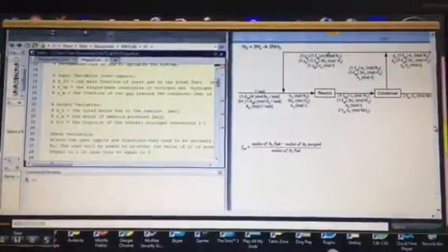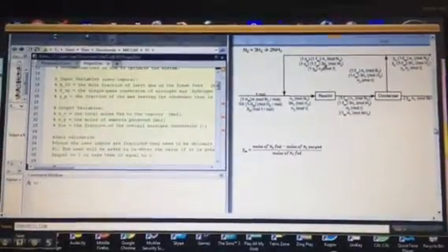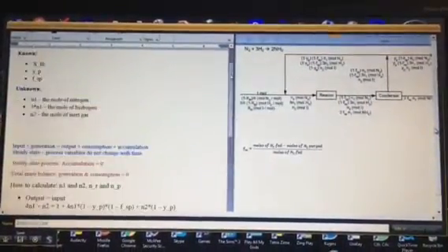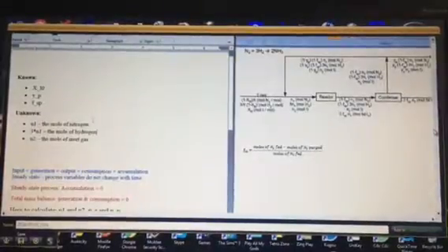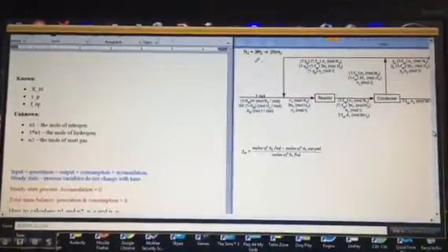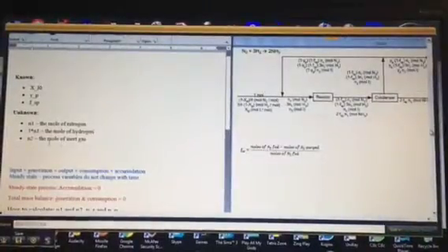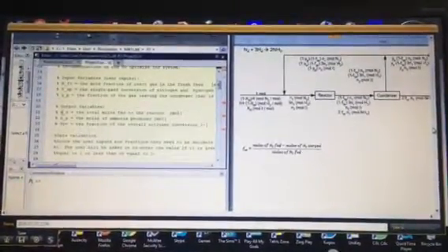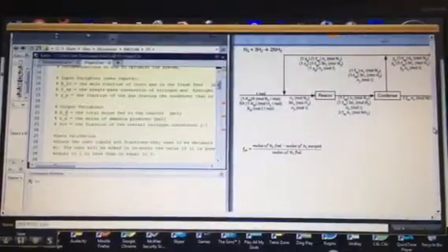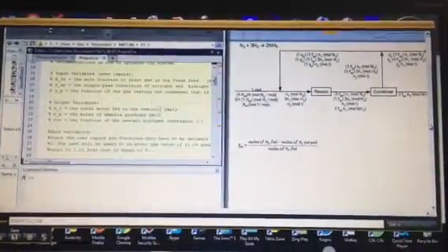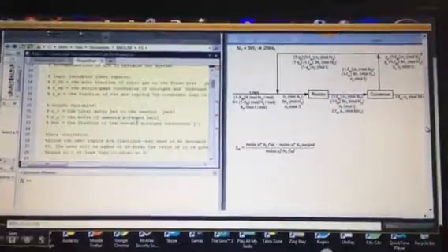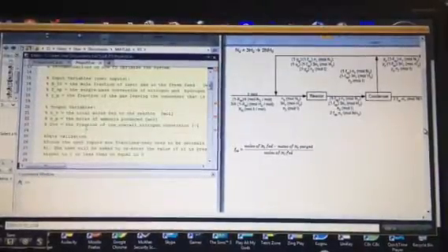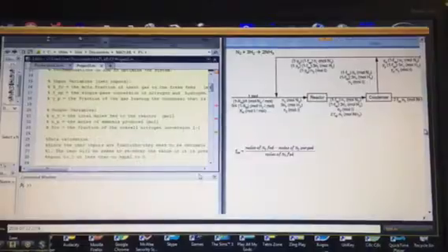However, we also have the N1 and N2. Because this is a stoichiometric process, we can assign N1 as our moles of nitrogen. Therefore, 3N1 is going to be the moles of hydrogen, and N2 is going to be the moles of inert gas, excuse me. For our outputs, which we want to calculate, we have NR, the total moles fed to the reactor, NP, the moles of ammonia produced, and FOV, which is the fraction of the overall nitrogen conversion.